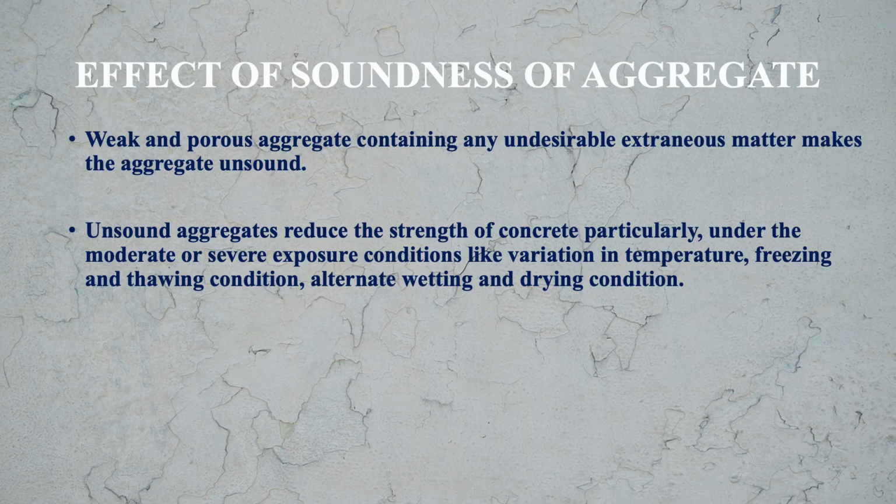In case of moderate or severe exposure conditions like variation in temperature, freezing and thawing, alternate wetting and drying, if we use unsound aggregate, then certainly this will lead to reduction of the strength of the concrete.